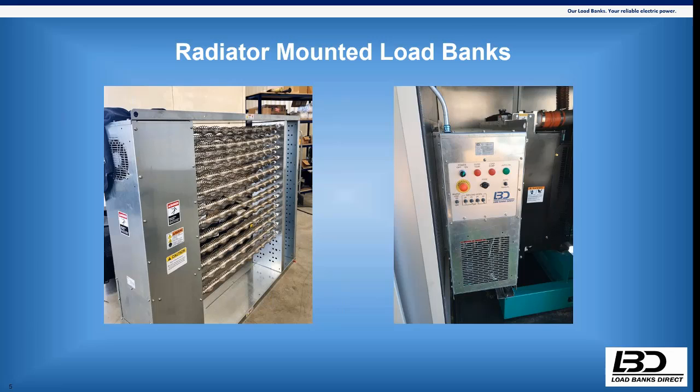Getting those dimensions correct prevents any type of heat issues. Sizing it, trying to keep within that 50% range, keeps us out of trouble. Yeah, that's a sweet spot, definitely on the non-self-cooling. So basically, on the radiator and roof mounted, that's the sweet spot for capacity, as far as making sure that it cools properly and you don't have any issues down the road with over temperature, cooling your generator properly, etc.